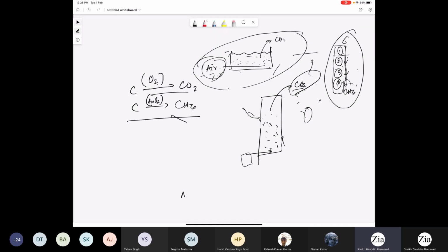Suppose the first reaction becomes very slow because of substrate limitation, then the subsequent reaction will not happen. So the bacteria for the subsequent reaction will not get any substrate, and they will die. Whenever you have death or depletion of bacteria, it creates a problem with the stability of the biofilm. You will have disintegration of the granule and instability of the reactor. That's why anaerobic reactors, particularly biofilm-based anaerobic reactors, are not preferred to handle very low strength or low carbon containing wastewater.